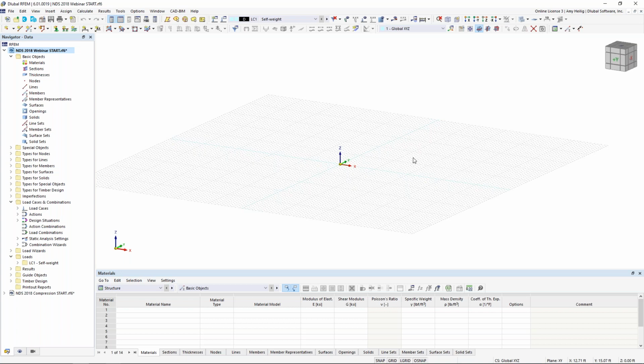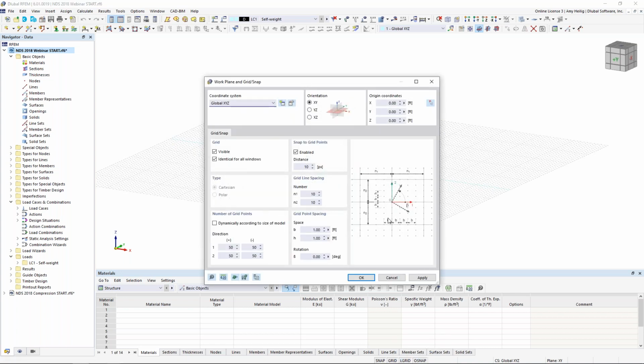So once we are done defining the base data, we will be brought into the main program, and we can see our drawing grid activated here. We can modify those drawing grid settings by right-clicking at grid down at the bottom. My default spacing here is set at 1 foot. If we see anything other than this, for example, when you first start the model, you might see something like around 3 feet. You can always hit this default option here to go back to the 1 foot or adjust this to maybe 0.5 feet. We can also open up our units here and change this to inches if we're working on a much smaller scale.